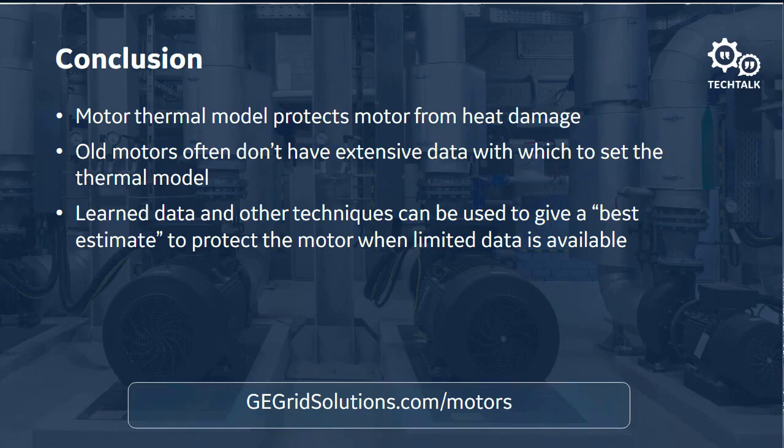So the art portion is: do I really want to do that? How much do I want to do that? Do I want to go to the 125%? You never want to go over the 125% because then you're not going to have your cables protected. But do you go to the full 125%? Again, that's an issue of the art and science of this.